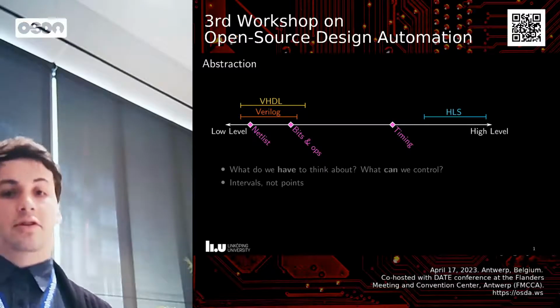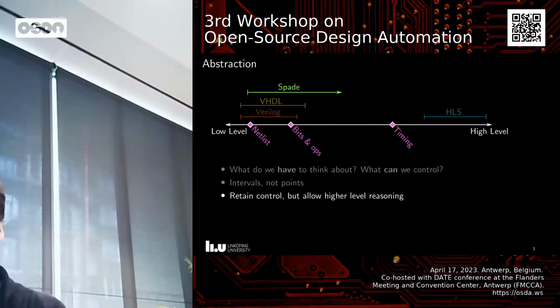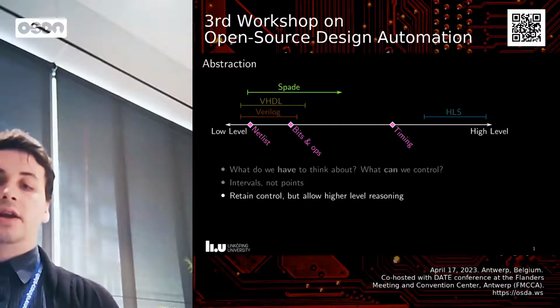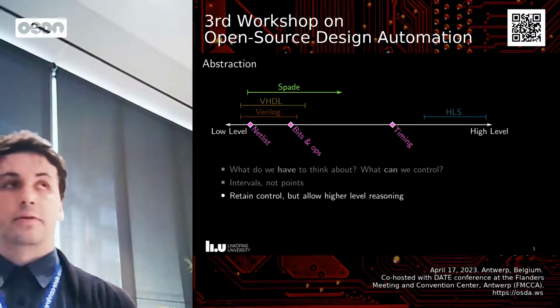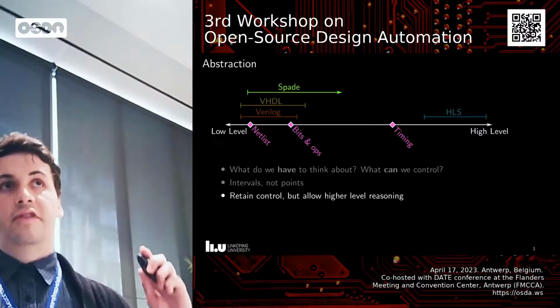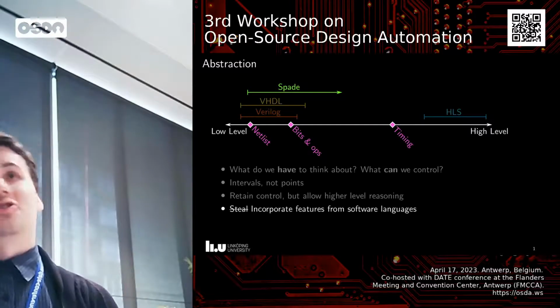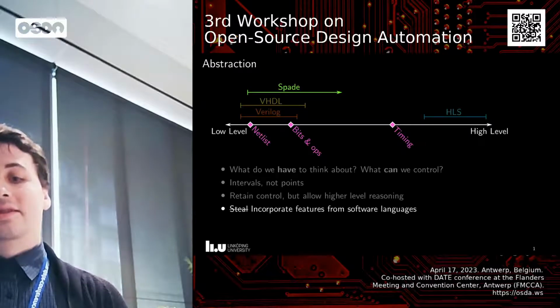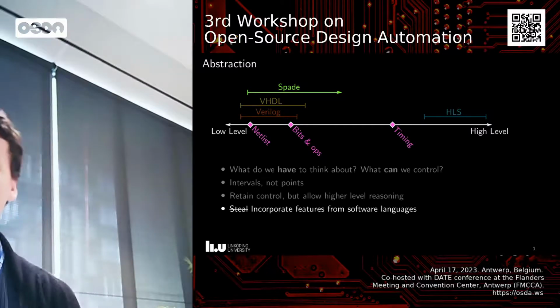Now, Spade is absolutely not a high-level synthesis tool. Just like BlueSpec, it falls on the lower end side of the spectrum. And the goal with everything I'm trying to do here is to retain the control that you have with Verilog and VHDL, but push the amount of high-level reasoning you can do while still retaining that control. I also want to steal a bunch of stuff from software languages, because I'm a software developer, and I miss a lot of things when I come to Verilog and VHDL and other HDLs.